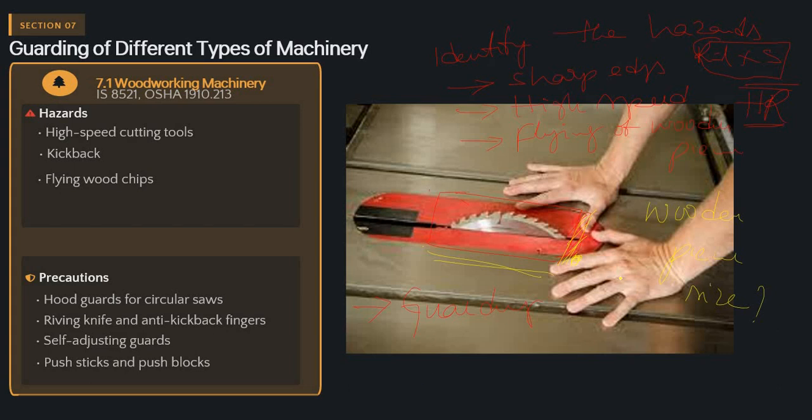So we need to provide a fixed guard around the three sides, and an interlock. Here we use three fixed guards and one interlock. Apart from this, here we put an adjustable door, a mobile door, with an interlock. You people mentioned a door, no? So that is an adjustable door, the front door, adjustable guard we can say, and interlock guard. So these are the three types of guarding we use for this simple machine.